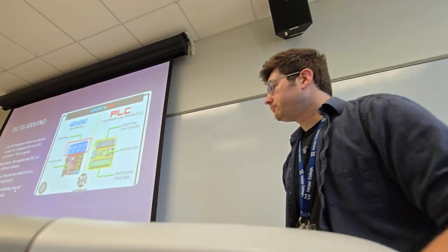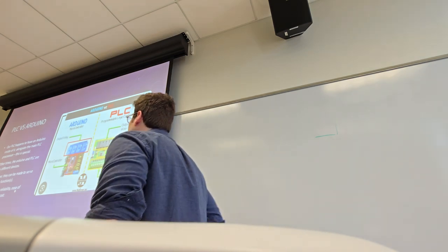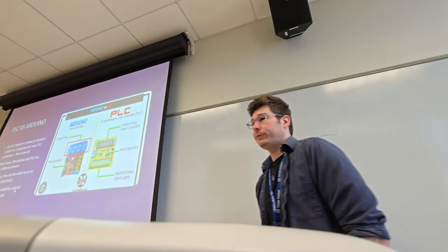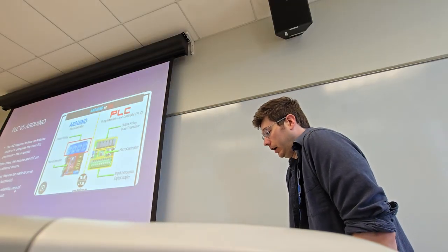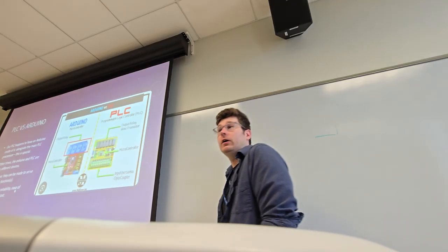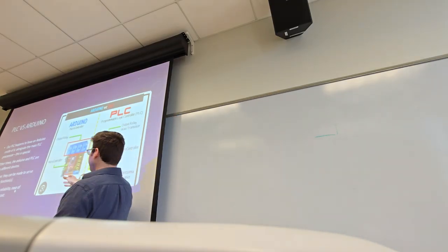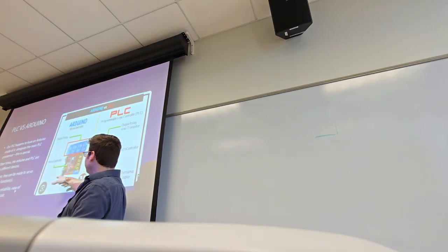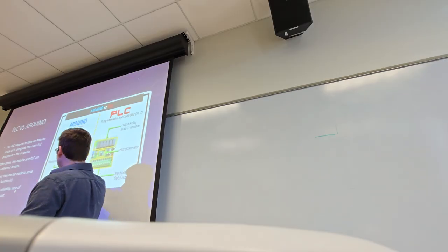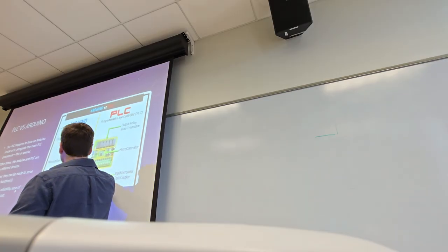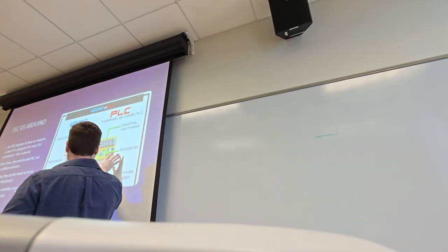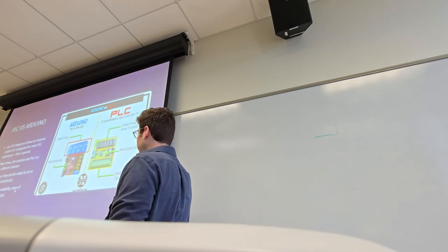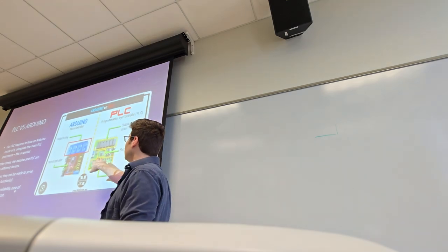All right, so all of that said, it might be a bit muddy in the water, like how exactly an Arduino is different from a PLC. It's confusing. You'd be okay if you were confused by this, because you could totally make an Arduino-based setup that has the exact same elements as a PLC. You could have it take 24-volt power, have a little power regulation down there to drop that down. You could install screw terminals to make it just like a PLC, have relays on there where some of your I/O pins are connected to relays just like we have on a PLC, okay?